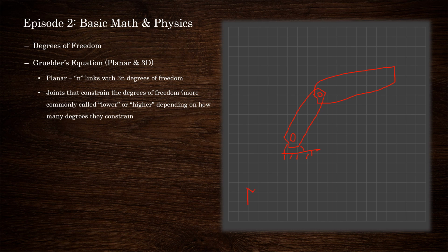So mobility is given as 3 multiplied by the number of links minus a ground link, because that loses all 3 degrees of freedom, minus, if you're losing 2 degrees of freedom with f1 number of joints, and then if you're losing joints that have 2 degrees of freedom, they've lost one, and we'll call those number as f2. This is defined as the Gruebler's equation of mobility. So we'll know more about this definitely, but it's something to note.